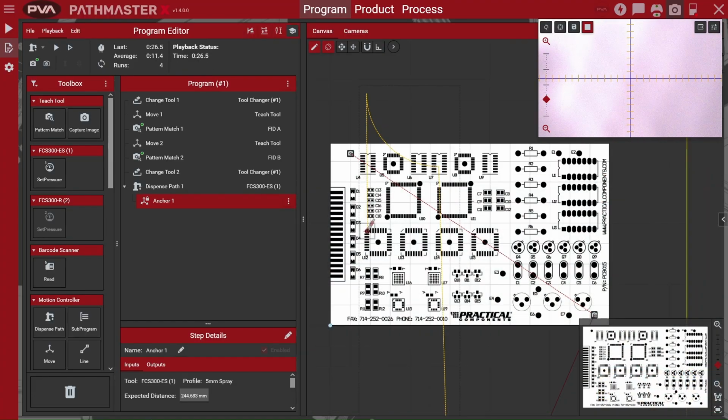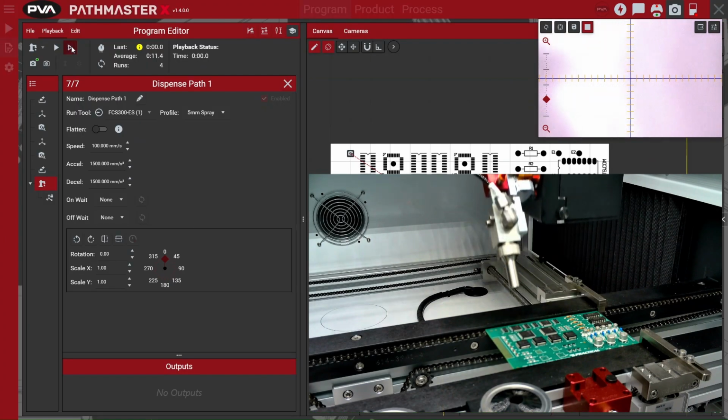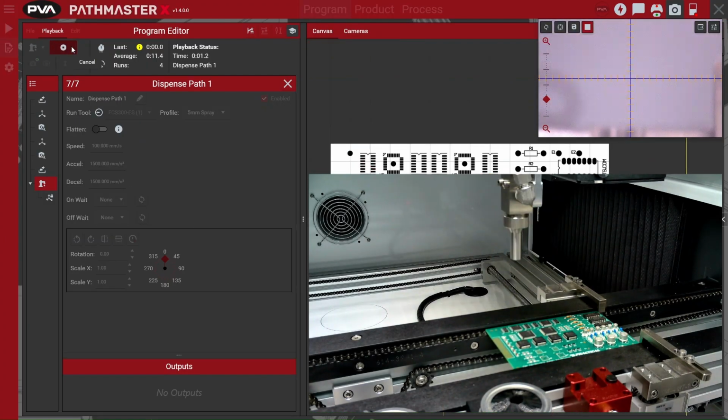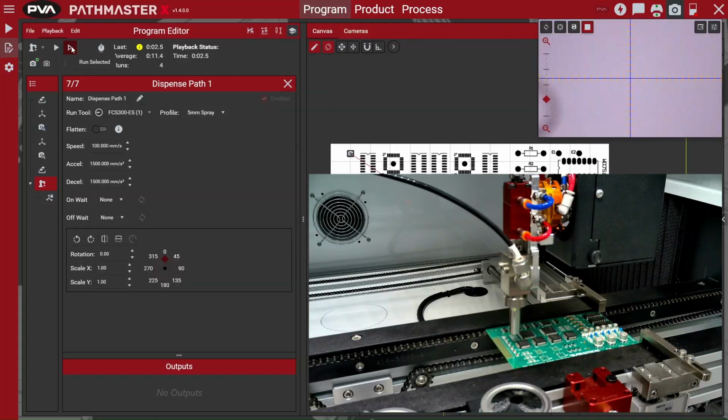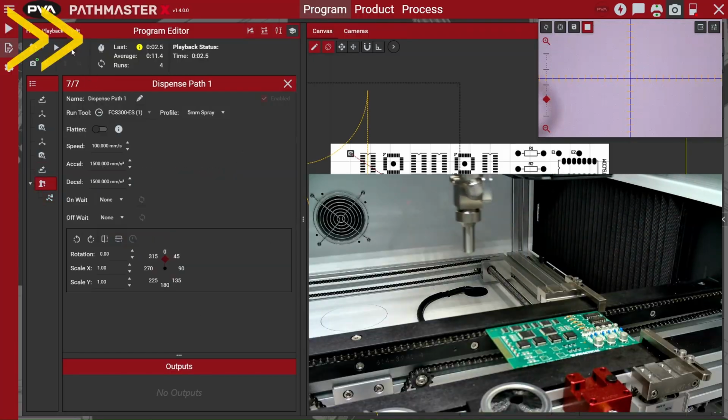The endpoint for the phi axis can be altered at any time, and the tool placement will shift the robot accordingly. Here, the angle is changed to 0, and the step runs to demonstrate the change. Here, the endpoint for both theta and phi are altered, and the step played to demonstrate the differing approach to the same point.